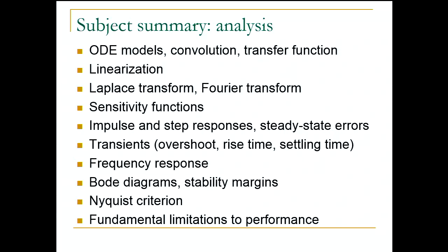And we also introduced stability margins using Bode diagrams, phase and gain margins, and all of these were based on the Nyquist criterion. So Nyquist criterion underlies most of the analysis in frequency domain. In today's lecture this morning, we saw yet another application of Nyquist when we talked about small gain theorem. Because small gain theorem guarantees that Nyquist will be satisfied robustly if some condition holds, right? And then we also talked about fundamental limitations to performance, both in time domain and in the frequency domain.